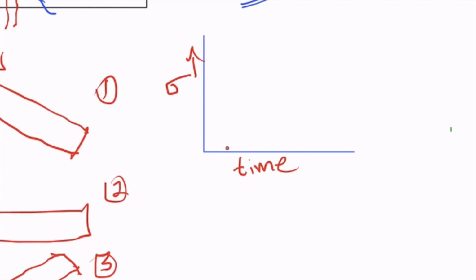When you consider a static load situation, the direction or the magnitude of force that we are not going to change continuously with respect to time. So if we go for a graph of a shaft bearing some fixed load, it will go just like this. That's a graph parallel to the x-axis.